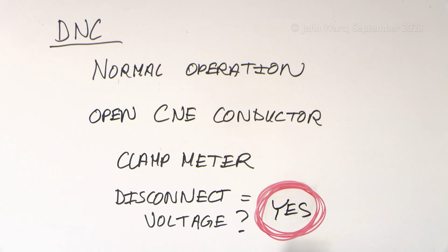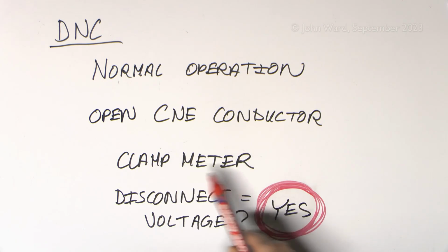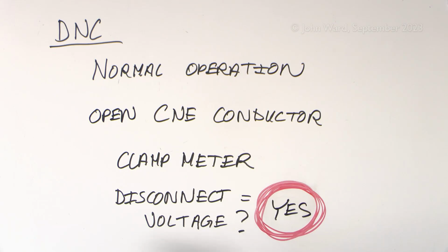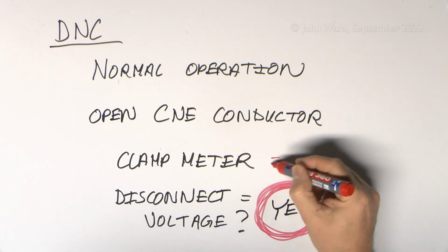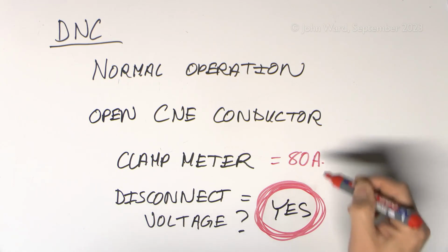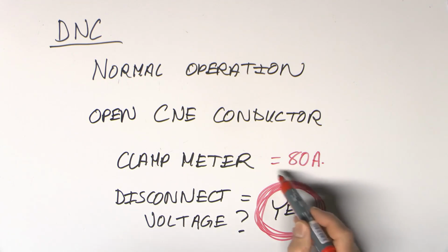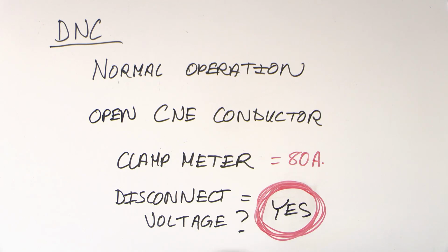What that probably means is that some load which was current flowing through that conductor you've disconnected, maybe next door or across the road or wherever, you've just disconnected that, someone else's stuff isn't going to be working. And again, this really comes back to how large was the current you measured before. If it was, say, a few amps or so, could be normal use. If you went to a property, say, and you found that there was sort of 80 amps going through a conductor, disconnecting it would be a very bad idea. There's going to be a significant risk of a huge spark there, or even arc flash coming out of that. Hence the reason to use the clamp meter first to get some idea of what's going on.